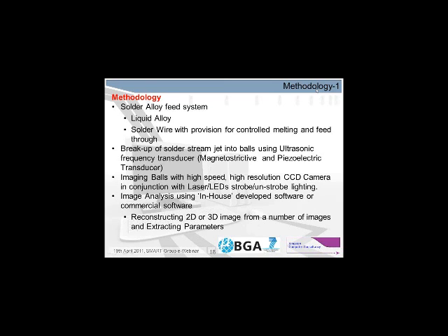We'll then be imaging the balls with a high-speed, high-resolution CCD camera, in conjunction with a lighting source: laser, LED, strobe, or unstrobed lighting. We'll then be using image analysis to analyze the consistency, the size, and the sphericity of the solder balls being produced.